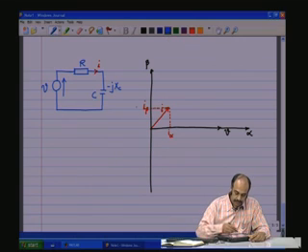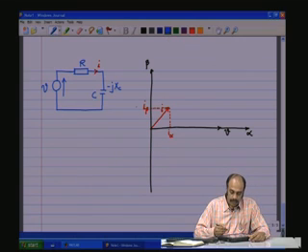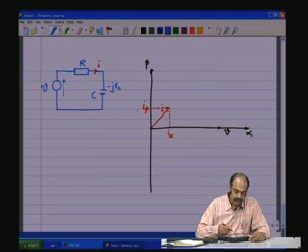Now, multiply all these with the voltage amplitude V. This being a phasor, when you are multiplying it with V, I mean that we are multiplying with RMS quantities. So, I alpha RMS with V RMS, I RMS with V RMS, I beta RMS with V RMS. So, relatively only the vector amplitudes will change.